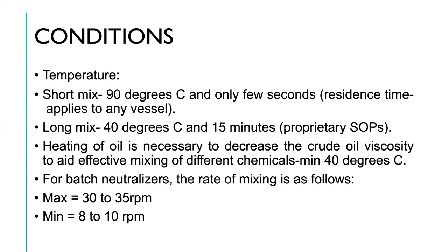So what are the conditions of alkali refining? Temperature for a short mix is 90 degrees Celsius and only a few seconds. Residence time applies only a few seconds. So this is your residence time, which applies to any vessel. Long mix, 40 degrees Celsius and 15 minutes.